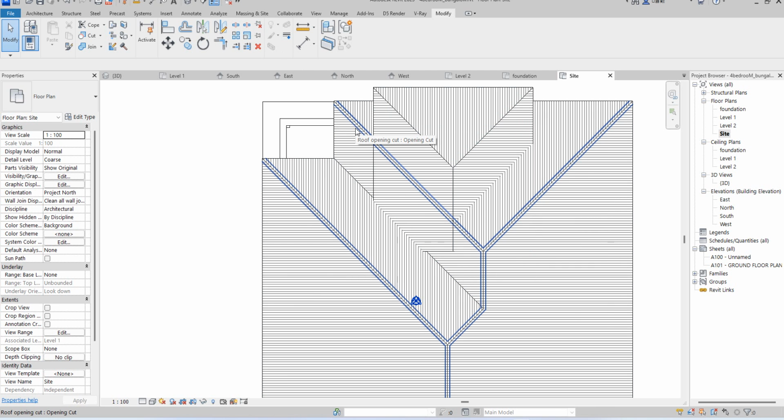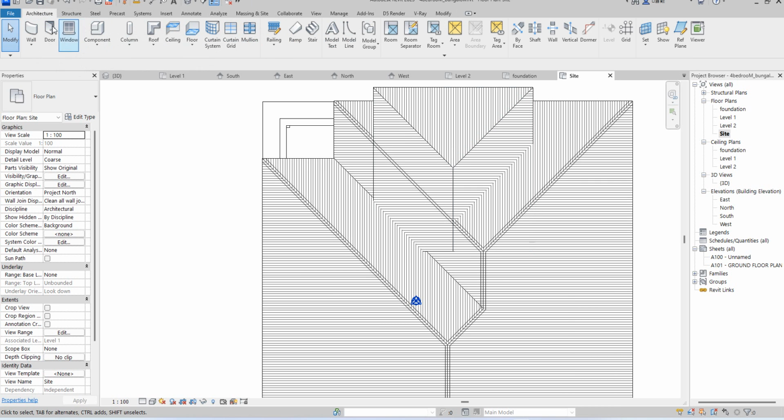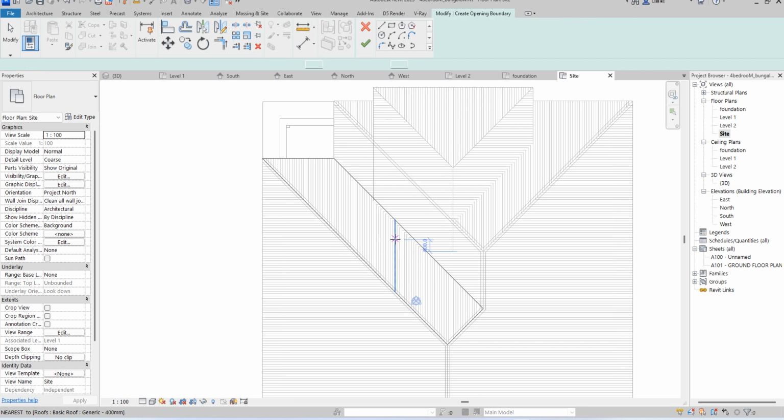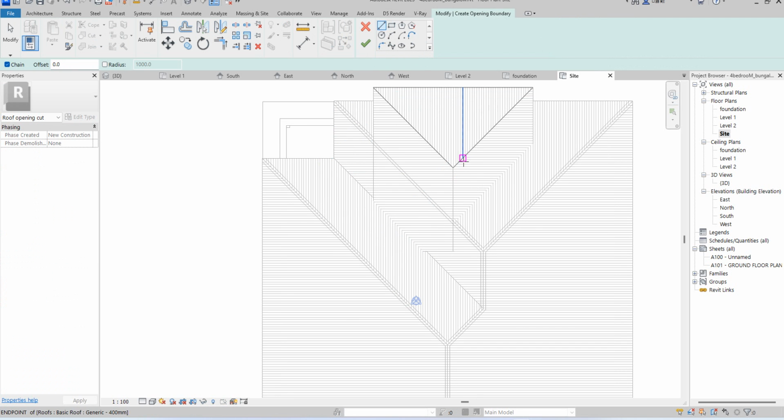First we need to cut this one off, but we need to get our ridge cap here before we do that, so that we don't have anything to be doing in the wrong direction. So now we go back and say go to architecture and say cut vertical. So you say for vertical now, then what do? So you start the process the way you are doing it before.